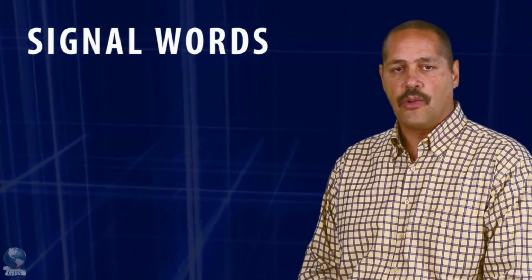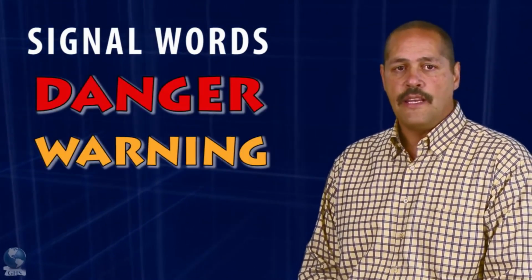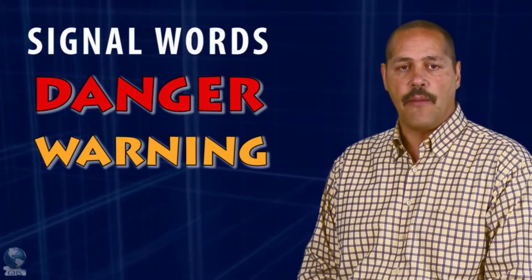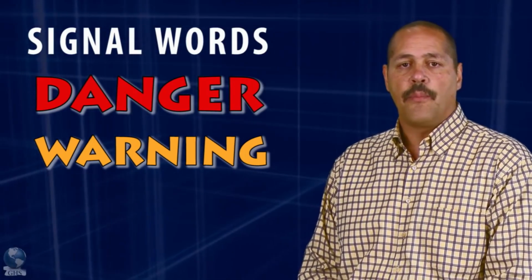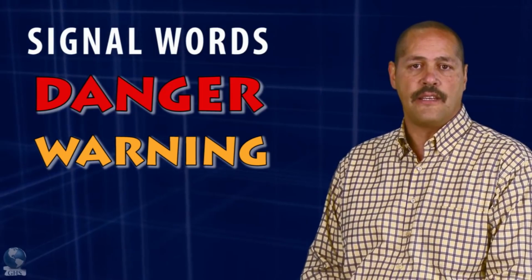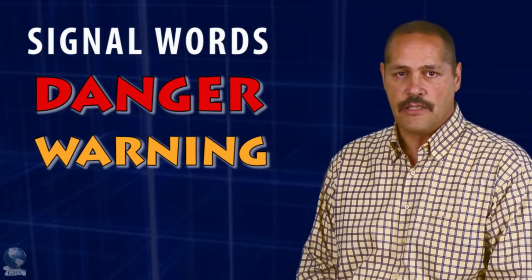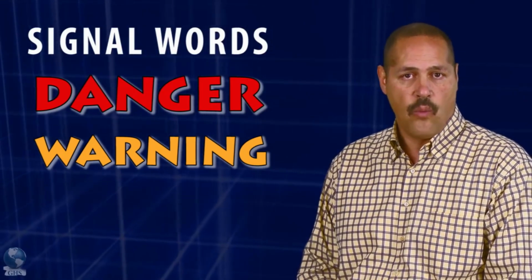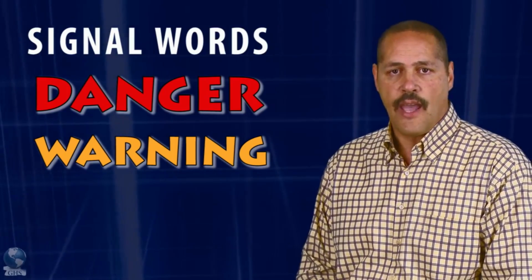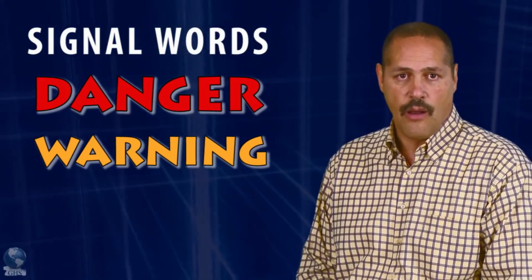There are two signal words in the GHS system, danger and warning. These signal words are used to communicate the level of hazard on both the label and the SDS. The appropriate signal word to use is set out by the classification system. For example, the signal word for self-heating substances and mixtures, Category 1, is danger, while warning is used for the less serious Category 2. There are occasions where no signal word will be called for.